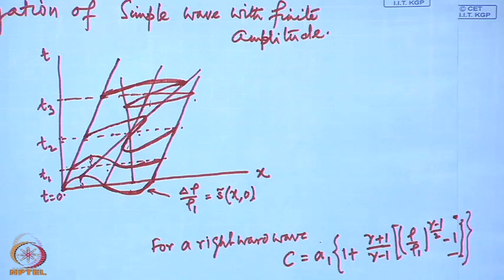Now, in the compression part, the isentropic relations are valid until the diffusive actions are considerable, or until the viscous friction and heat transfers are important. When the stationary balance between diffusive actions and the nonlinear steepening effect is reached, the conditions across this wave front are given by the shock wave relations, which we have derived earlier,